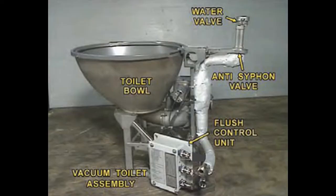Here is a typical vacuum toilet. The toilet bowl has a Teflon coating to prevent stuff from sticking to it. The whole unit is a line replaceable unit. The flush control unit, which is a sub-assembly, can also be changed independently of the vacuum toilet. This sequences the various valves in the flush cycle.